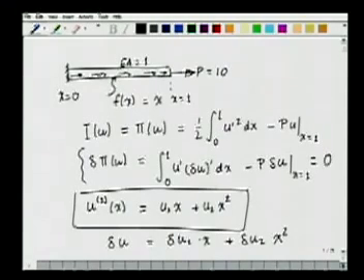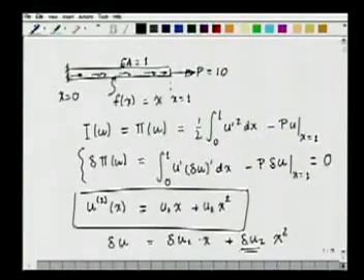It is the variation or the virtual displacement that we are talking about. So I can choose first, since it's under our control, delta u2 equal to 0, delta u1 equal to 1, and we'll get one equation. Then in the second one, we are going to set delta u1 equal to 0, delta u2 equal to 1, and we'll get the second equation. This we have done in the previous lecture, so I'm not going to go over it again.